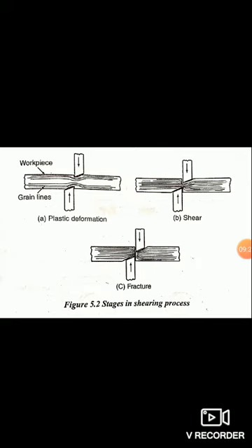When the blades begin to apply pressure, the workpiece will start to undergo elastic deformation. As the pressure increases, the workpiece will undergo plastic deformation. This is the first stage. The application of the pressure will produce plastic deformation.